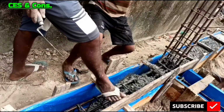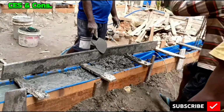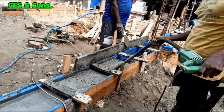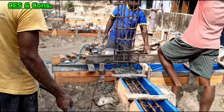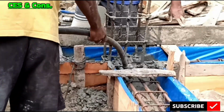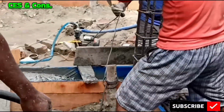The concrete is M25 grade and the water cement ratio is 0.45. A vibrator is being used where it is necessary. Using a vibrator during concreting is extremely important for ensuring good quality and durable concrete. IS 456/2000 states in clause number 13.3.1 that concrete should be thoroughly compacted and fully worked around the reinforcement, around embedded fixtures and into the corners of the formwork.